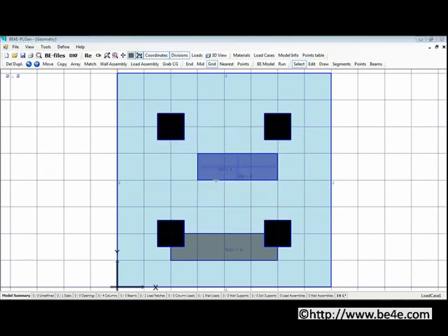The load assembly is a combination of several walls, usually very representative of cores over rafts in buildings. In order to create a load assembly, you first need to create the walls. So over here, I'm going to create another wall. First select the draw mode. Create another wall here. Right click. Then I'm going to create another wall over here. Right click. I'm going to go to select, choose it as a wall load, choose this one, and define it as a wall load as well.